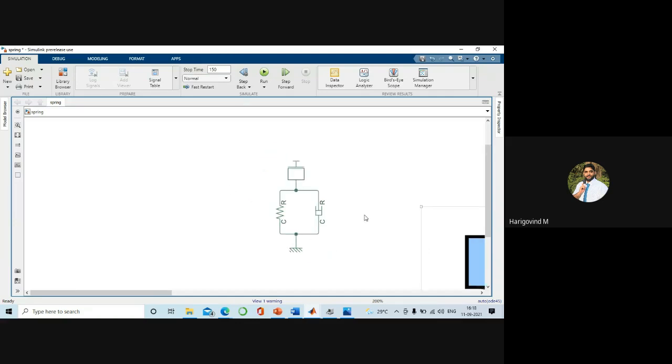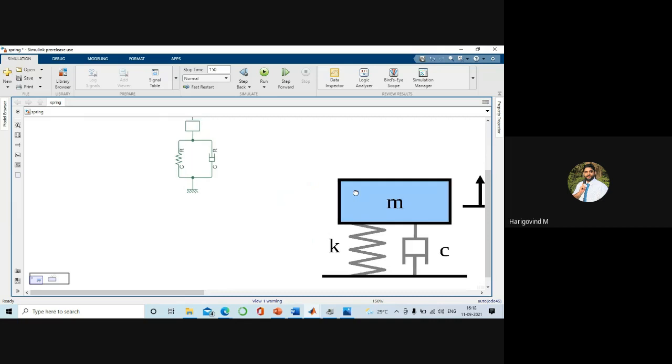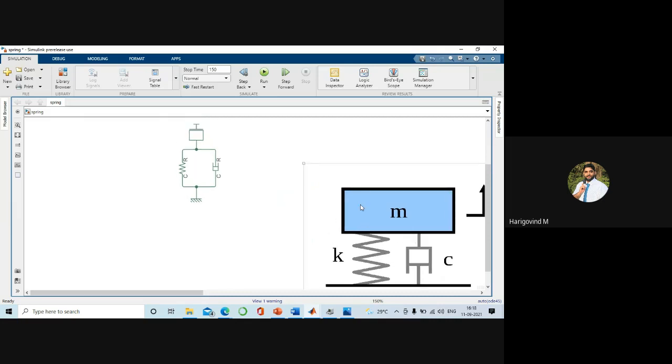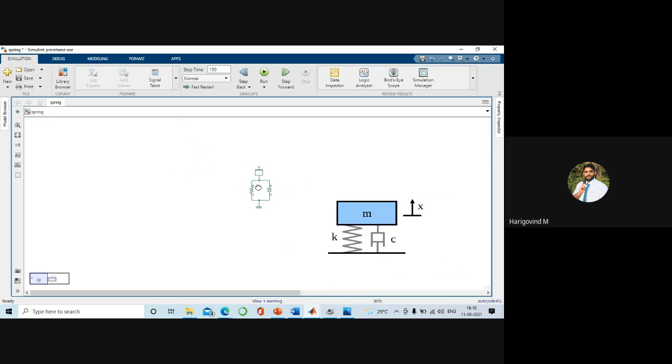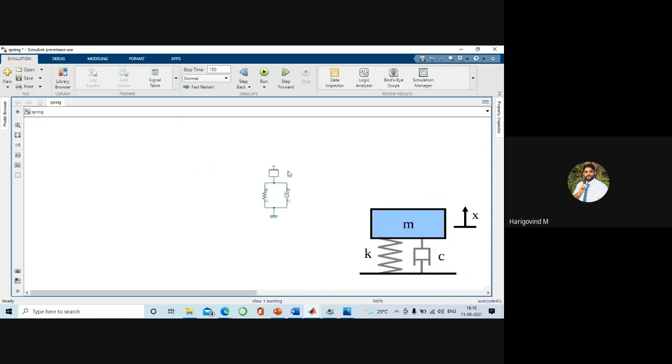Okay. Now the system is created exactly as in the given problem. This is a physical system. These Simscape systems are known as physical systems, so we need to integrate it with Simulink. Simulink only knows how to solve differential equations. If you press the run button, it creates differential equations, solves them with numerical methods and plots accordingly. But since this is a different kind of library, even if we press run, there will be an error because Simulink does not know it.